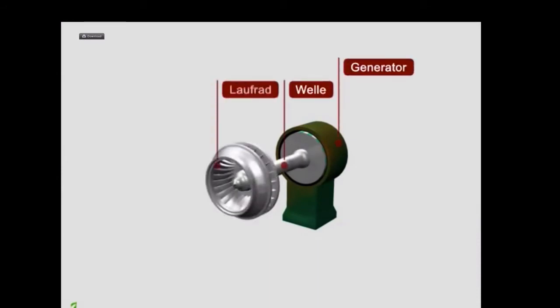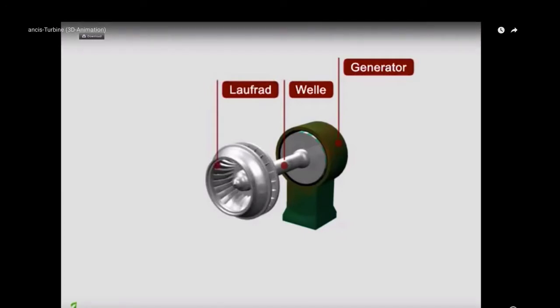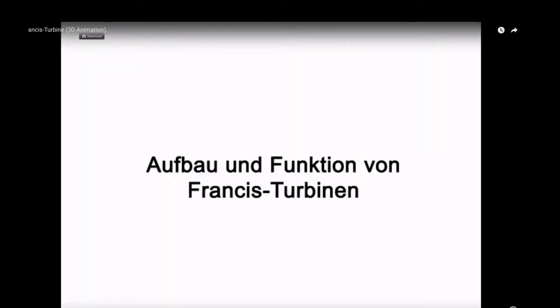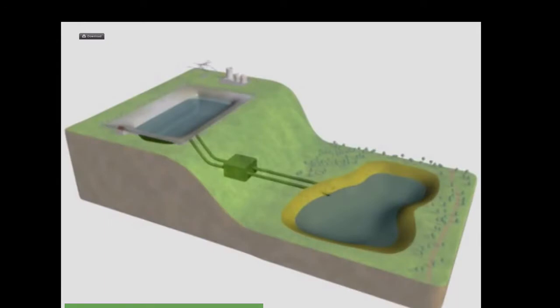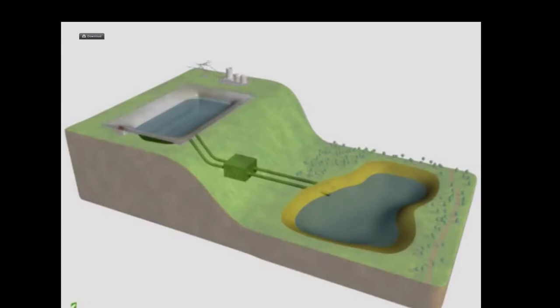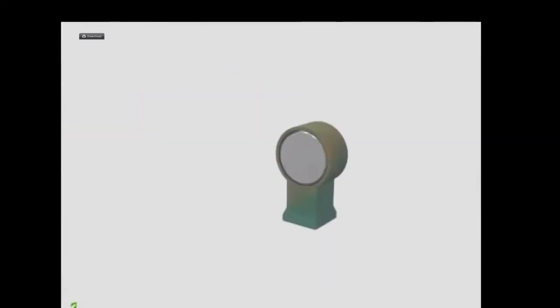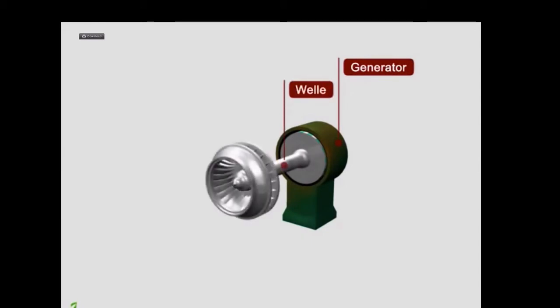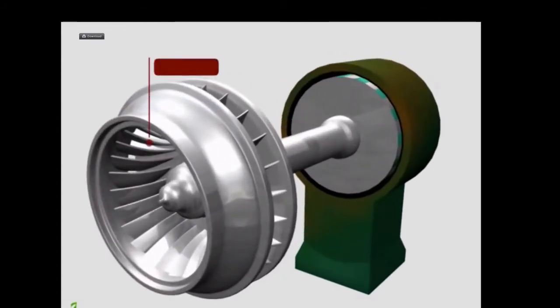And so one way to do it is a pump storage scheme, which is shown here. That is the idea that you pump water from a lower reservoir up into a higher reservoir at nighttime when electricity is cheap, and then when the demand comes to peak in the daytime, when everyone turns their toasters on at 7 o'clock in the morning in New York City, then you run it back down through to give you extra capacity. And so you can actually build less capacity into your system by using storage mechanisms like this.